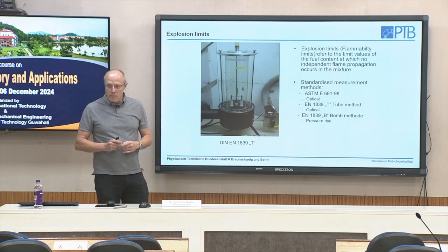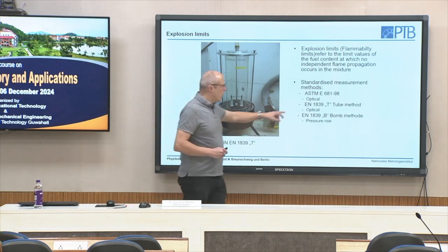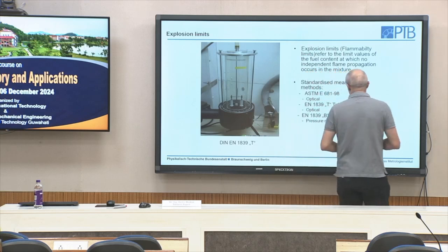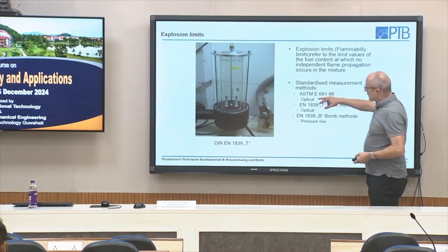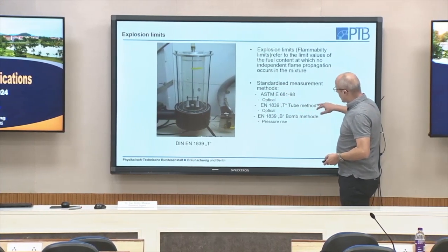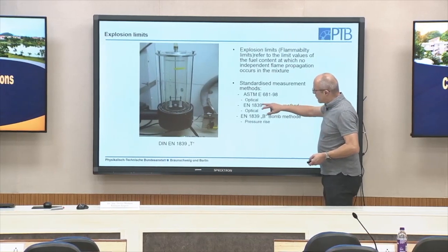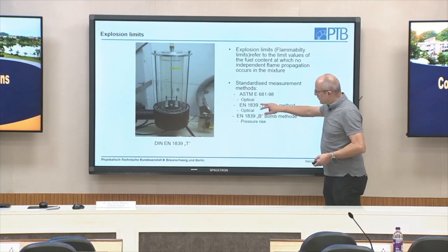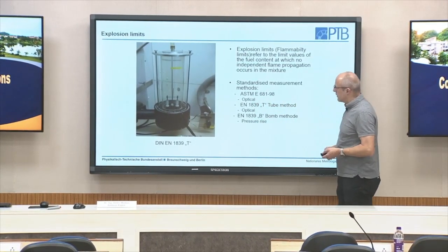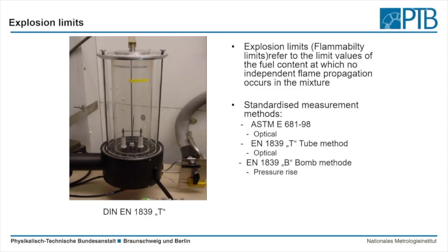So there is the ASTM E681-98. They have an optical criterion. In Europe we have 2 methods based on the standard EN 1839. We have a tube method where we have an optical criterion, and we have a bomb method with a pressure criterion.